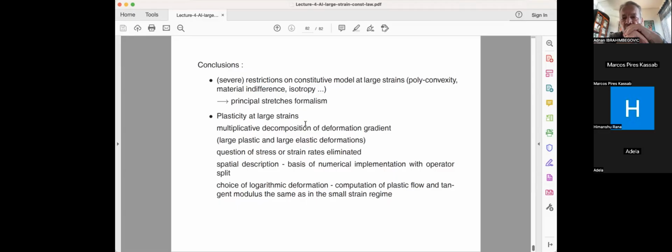Please recall that in all these developments, the main hypothesis is about isotropy of the elastic response. But that fits nicely into many materials of interest for engineering applications, for example, steel, aluminum, and stuff like that. This is fine. Even the concrete, which is kind of a crazy composite material, is statistically speaking, an isotropic response and stuff like that. If you have anisotropy, then you have to deal with the discrepancy between the principal direction of the strain and principal direction of the stress. Some people have done it. You have exponential type of approximation, stuff like that, but it's really never a clean development because real life is never too clean. What can you do, basically?